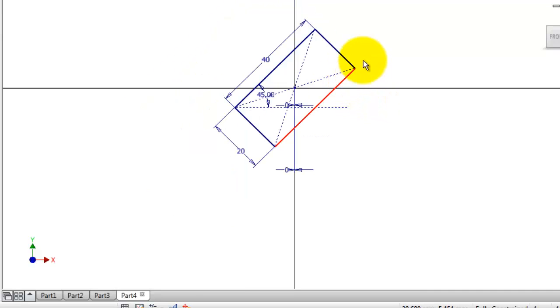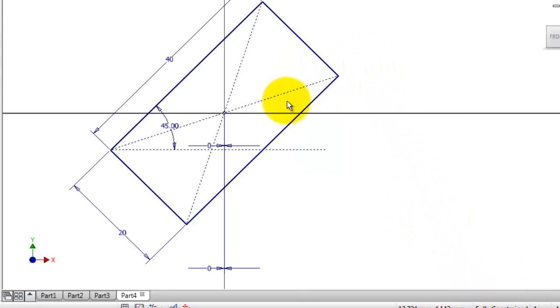And now we have the rectangle fully constrained. But as you notice, we use dimension 2 times in order to center the rectangle with the origin, but we can do it just in one step by using the constraint, which will be the topic of the next tutorial.